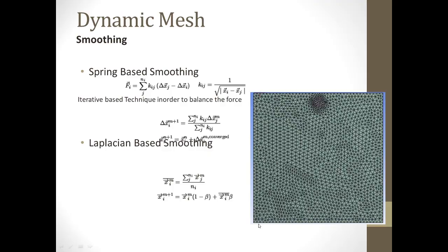In order to solve for c, we need the value of velocity at the initial time. As we have gently placed the sphere inside the water, there would be no initial velocity. So at t1 equals 0, v1 also equals 0. Applying that to 8.26 t plus c, we get c equals 0. So the velocity is 8.26 t. This is how the sphere velocity changes with respect to time inside the water. Please do remember this; we'll apply it in the simulation part.